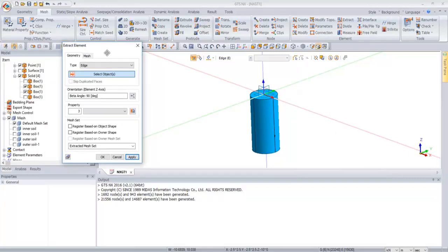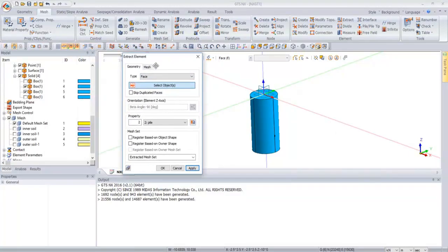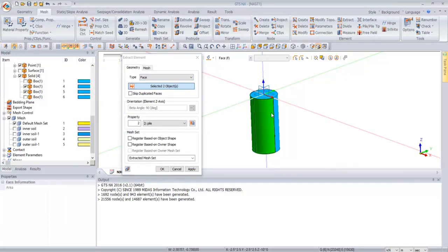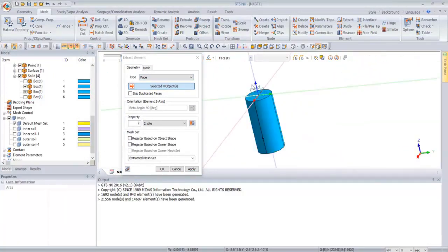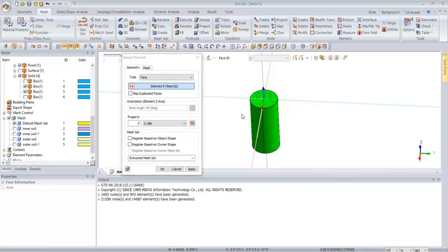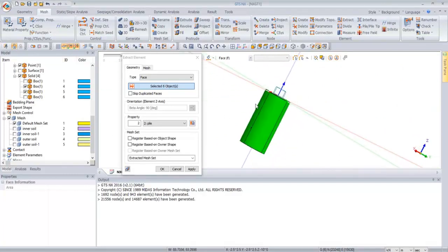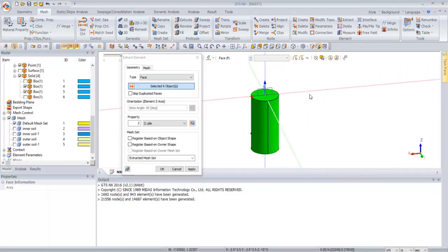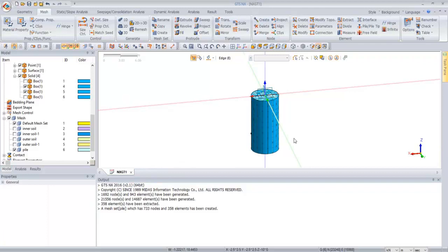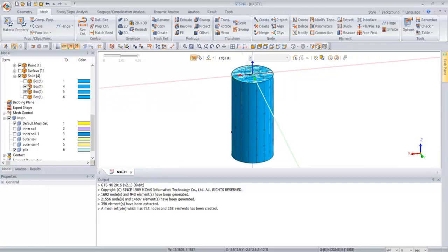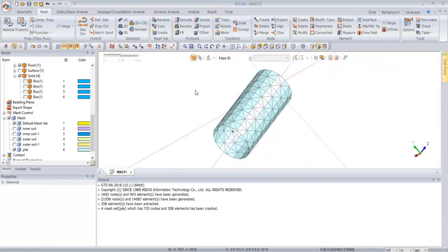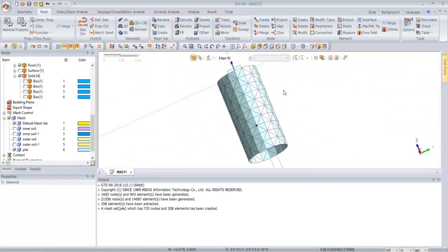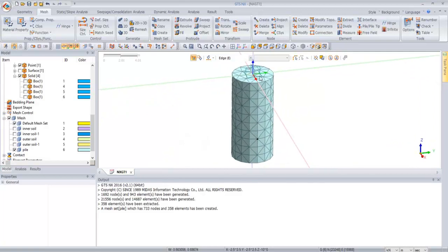And so I'll select from here the type face, since it's a geometry face. And I'm going to select the 4 outer walls and then the top faces. See, we're leaving unselected the bottom, and because it's a shell element, it'll be hollow. It'll leave it hollow inside. So this will just be the pile. And we're already assigning the structural property of pile, but we'll notice that the nodes actually coincide to the location of the already meshed ground, so they're connected. But we see here, this is exactly what we wanted, a hollow pile itself, but the top, it's a suction pile, so the top is also there.